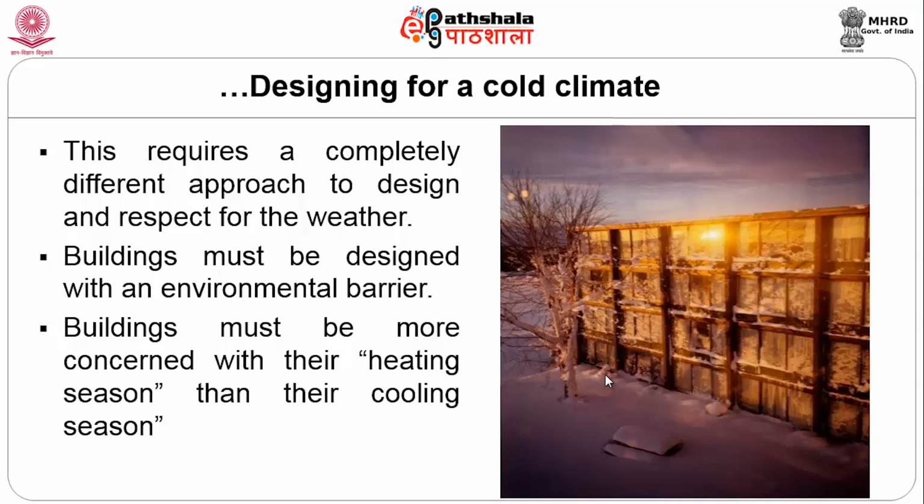So, how do you go about designing for a cold climate? You need to have a completely different approach to design and respect for the weather. Buildings must be designed with an environmental barrier. You have to be more concerned with the heating season rather than the cooling season, because in a cold climate the summer season is a much shorter period. So, if during the summer months or a couple of months they do require electricity to keep the building cool, it is fine, because the majority of the year the climate is going to be cold, and we need to ensure that the heating season does not consume a lot of electricity. So, within the realm of the seasons, we need to choose the better of the two options and go ahead with that design.